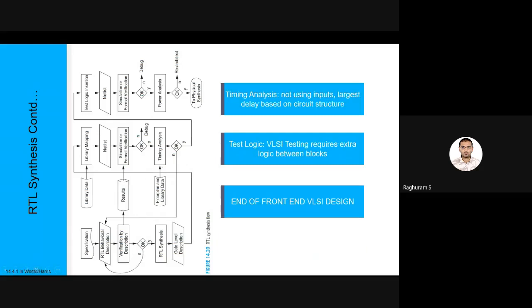So the next step is the timing analysis. Timing analysis means that now we have to use the layout information. This is where I said that the layout is not just the diagram of a gate. It is also the power and timing information. So some person has sat there, and again this is a job of a VLSI engineer. He has drawn the layout using some tools, and he has extracted it. The layout is in terms of rectangles. It is in some particular material, silicon, metal interconnections, etc.